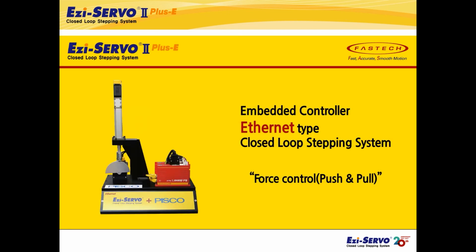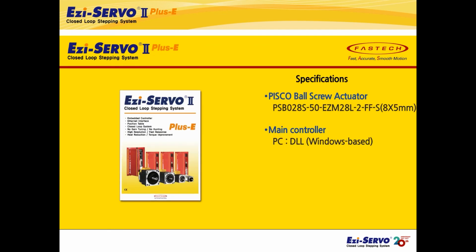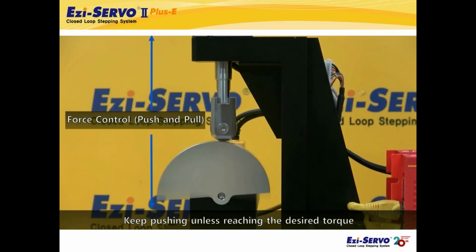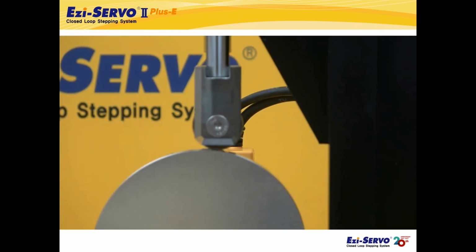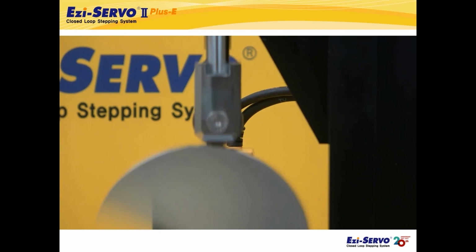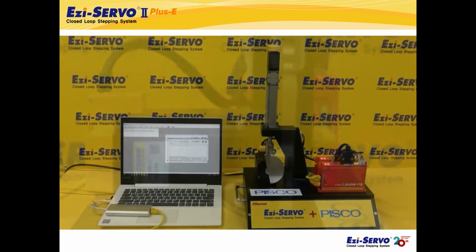In addition, Ezi-SERVO Plus-E provides a force control function. In this demonstration, the upper motor is pressing the half disc with a certain amount of torque, and the lower motor moves the position of the work. The product names used in this demonstration are as follows. In the position control method, when the lower half disc moves, an alarm occurs because the position value of the upper motor changes. However, if it is driven by force control, it does a constant pushing motion with a certain amount of torque rather than a position value, so an alarm does not occur.